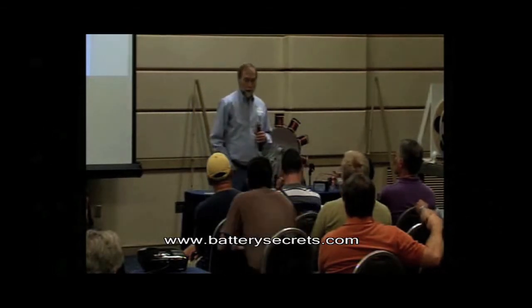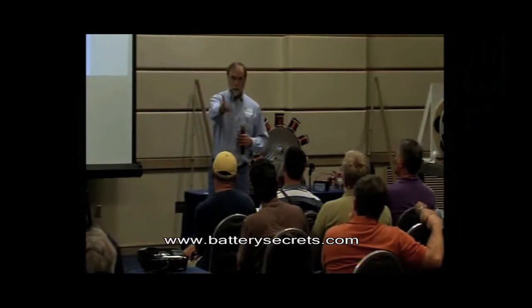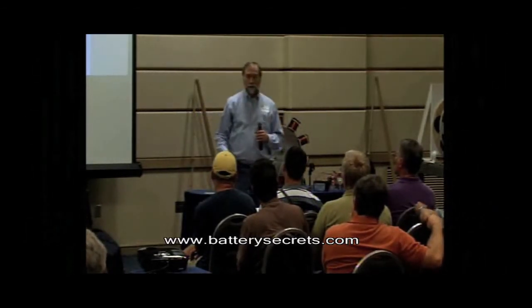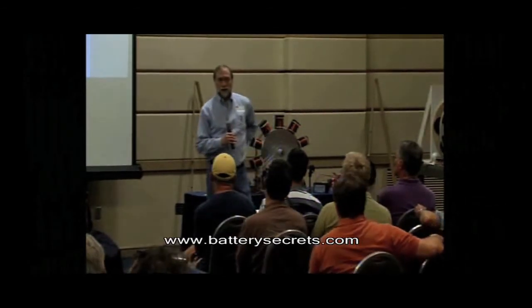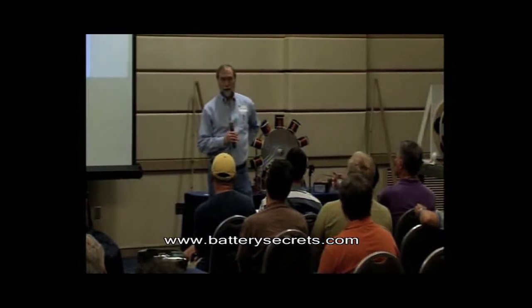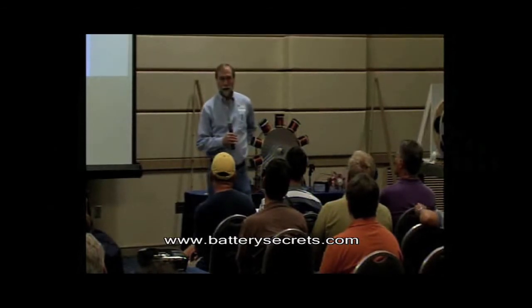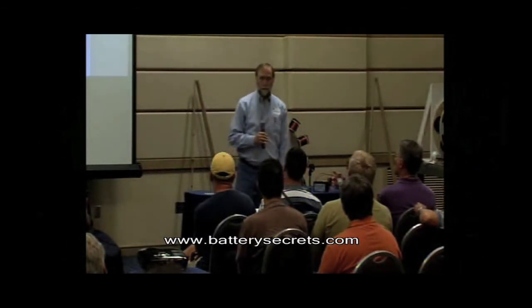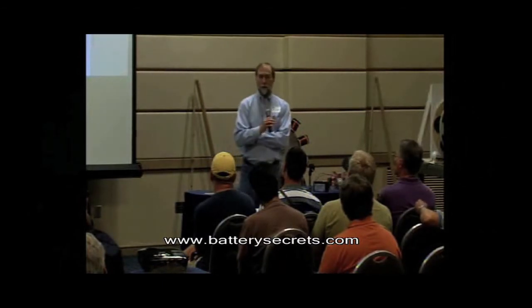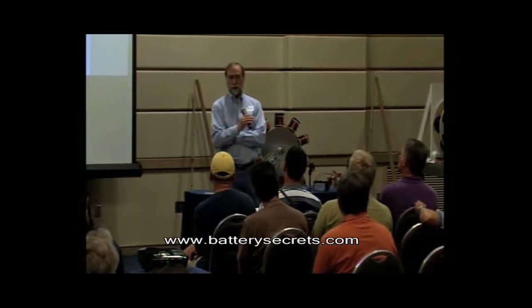How do we reform it though? Well, the way to reform it is to go back and do forming. In other words, discharge it completely and then start flipping. Well, see, here's the problem. When you discharge completely, you end up with 2 plates that have a lot of lead sulfate on them. Then you can turn it around and see what you can do. It can be an expensive failure because you're not used to the process or how long it takes and how many cycles you may have to go back and forth charging and discharging and so on.